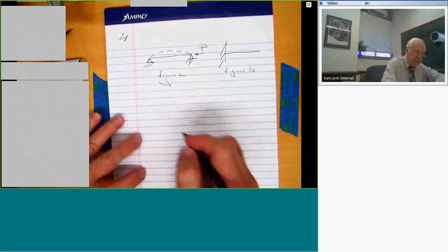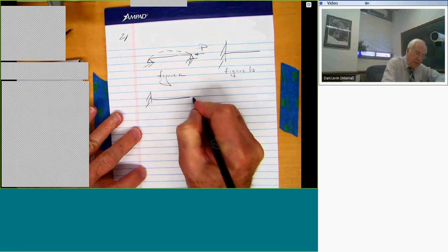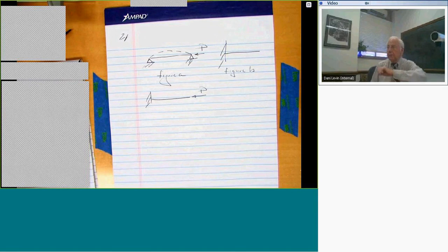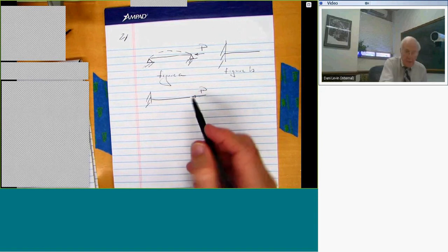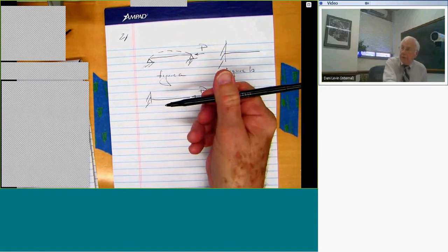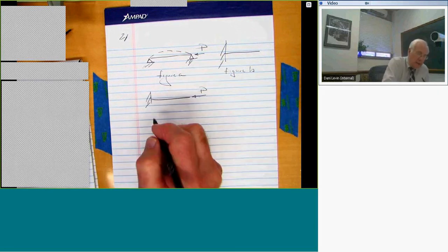Now, it turns out, by the way, if I had a cantilever beam and I press on it this way, it'll still buckle, provided that, in both the mathematical model and also the experiment, I'm very careful to keep the force P in the horizontal direction. I don't allow it to change direction, right? That's sort of the classical buckling problem.